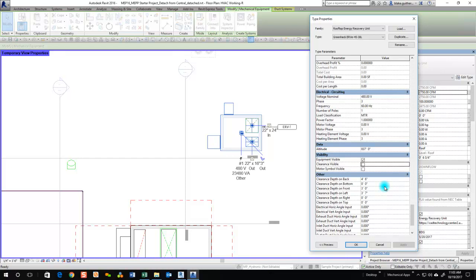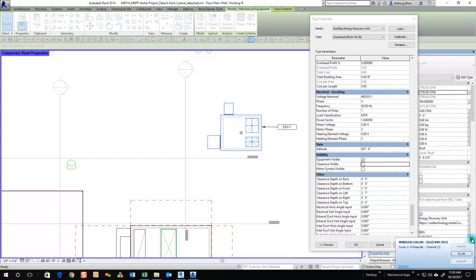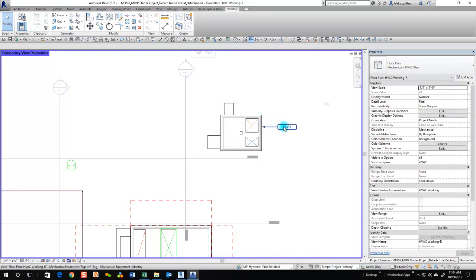If you're using clearances, we'll continue to educate architects and other disciplines, but we need to make sure that they know how to turn off our clearances. We need to instruct them: go to generic models and turn off that subcategory for clearance. Otherwise, if you've placed a family and you know that you're all set with your clearances, I would turn this off, because then you don't have to worry about the architect or another discipline not being able to isolate some of your subcategories. So that was just one family.